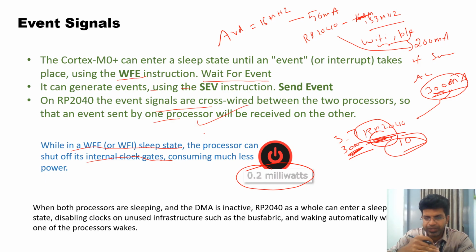So whatever the situation is, it is not necessary to measure the water level every 5 minutes. The water level change in 5 minutes is not going to make a big deal. So what you can have is, I can set a timer for 30 minutes, and only at a regular interval of 30 minutes, the sensor will turn on, check the water level, and turn off.